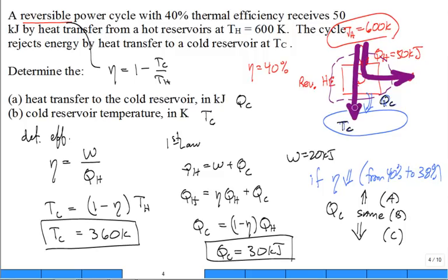The best heat engine will convert most of QH to W. The reversible heat engine is the best. If you start to have some irreversibilities without changing the temperatures TH or TC, the hot and the cold thermal reservoirs, which we don't change, and the system's performance degrades due to the presence of irreversibilities, more waste heat has to be dumped to the atmosphere. QC has to go up.